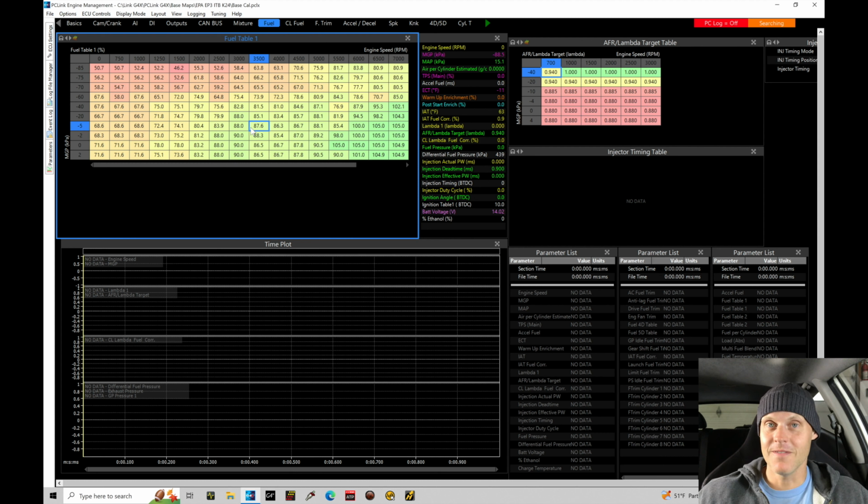We're going to be doing this very specifically so that we have a table that represents low and high cam, or non-VTEC and VTEC, operation. This is exactly how Honda calibrates with the factory ECU. We want to mimic that to give the best drivability and the most repeatable and consistent power output from our Honda K-Series engine. Let's jump in and take a look at how we can accomplish this.